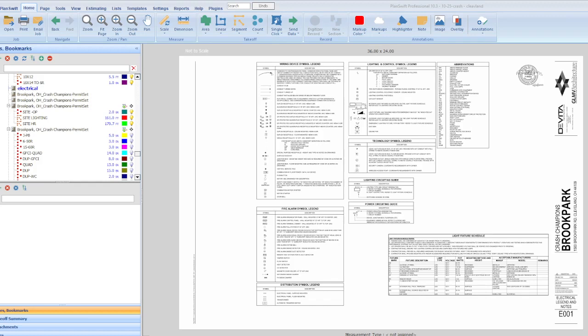You have to pay good attention to detail. All the symbols look alike, but they are not, and you'll find a lot of mistakes. So the biggest thing about producing the electrical estimate is that you have to have a good counting tool, one that will assist you in counting and help you in not making mistakes.